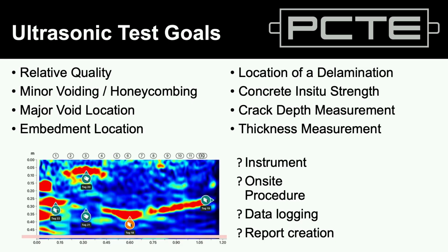We've done this each time, except a little bit during corrosion, because that was Ruben's presentation. What do we want to know? Do we want to compare quality, like with the Schmidt hammer? Do we want to get an idea of whether this concrete's the same as this, or this concrete's different to this? We can do that. If we can get a nice, clean bit of homogeneous concrete, do a pulse velocity test or one of these other tests, the result will change if there's some qualitative difference between it, maybe a different strength, or maybe if we've got some minor voiding or honeycombing, if the consolidation is bad.